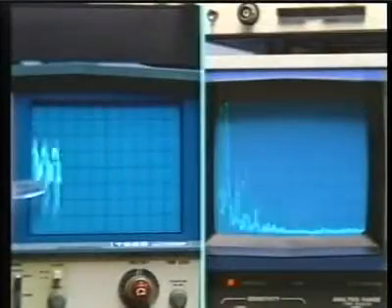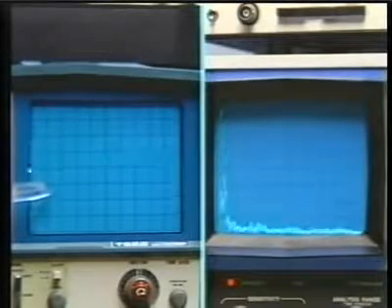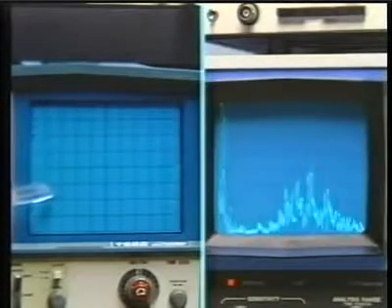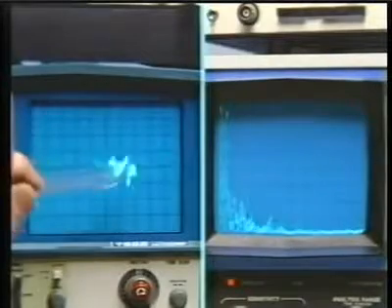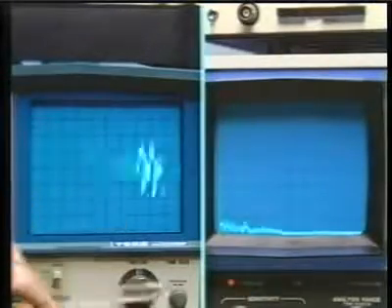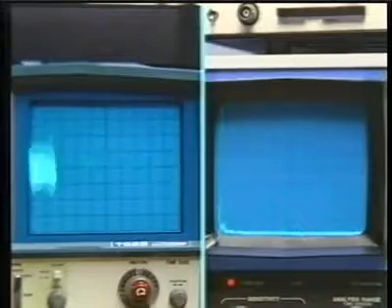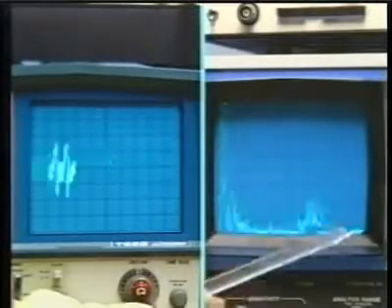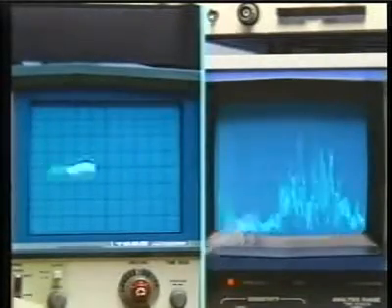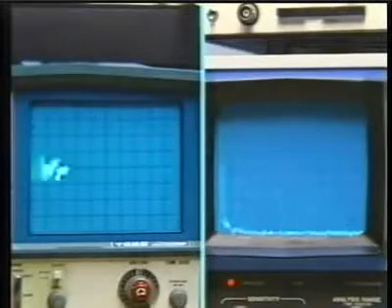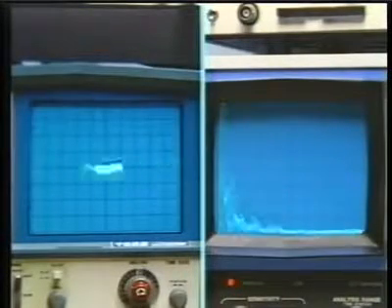The telephone company just filters out everything outside of that and thinks of that as a speech signal, so it doesn't have the high fidelity that you might have on hi-fi equipment. As we look at the scope, again, the time waveform is extremely complicated. Seems to have some periodicities in it, although they're short-lived, and then it goes on to some other periodic chunk. And over in the frequency domain, you can see as we extend from 0 to 10 kilohertz that as I speak, there are transients that have spectral content in them covering that entire band.